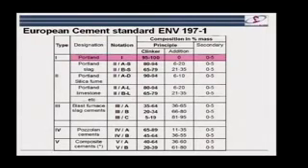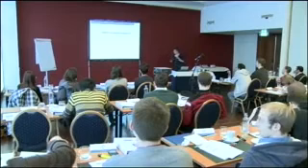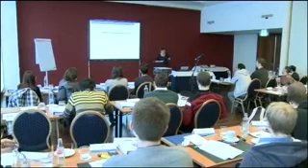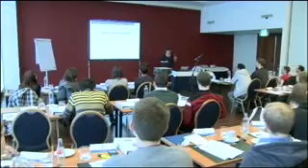But even this CEM I can have 5% of secondary addition, and virtually all cement you get in Europe today will have 2 or 3% fine limestone, because fine limestone, at this small level, improves the properties and lowers the CO2 emissions. So even a CEM I will almost certainly contain small amounts of fine limestone.